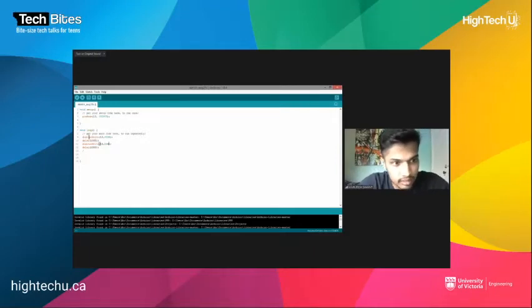So now you see that I am writing the digitalWrite command to pin 13 as HIGH, so that will turn on the LED. I will wait for 1 second, then I will write the digitalWrite command for pin 13 as LOW. That will turn off the LED for 1 second.